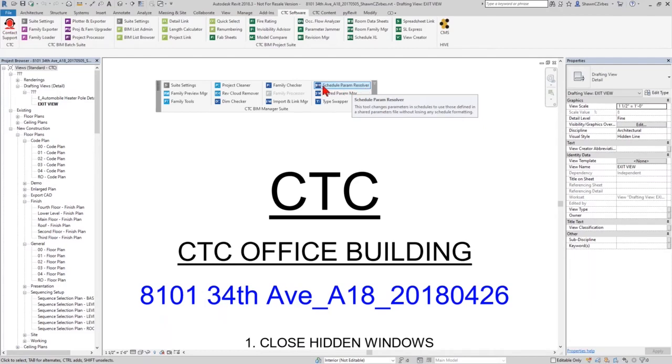This tool helps you laser focus on the parameter that is actually in your shared parameter file, fix your schedules accordingly, and then as you bring your families into compliance with a tool like Family Processor, when they get used in that project, they'll just work the way you want them to. So it's a great partner tool to your family cleanup process.